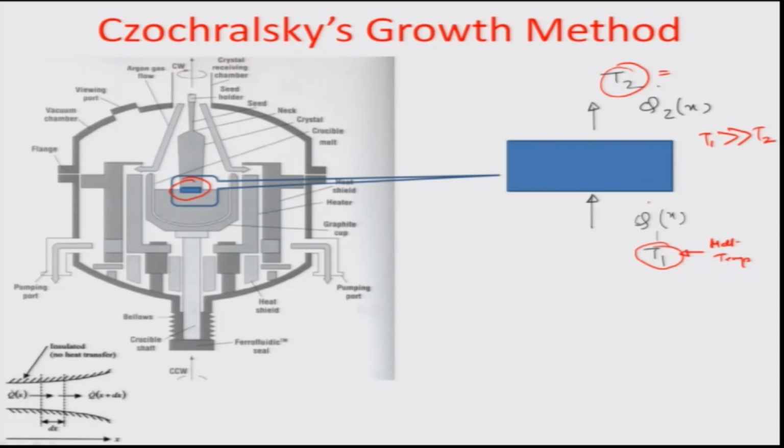is going to be a heat flow across this particular boundary from liquid into the fusion zone, into the solidification zone, and then there is a heat outflow from the solidification zone into the solid metal, which is Q2 dot. So, there is a rate at which heat is flowing in to this zone, you can call it zone of fusion or zone of solidification, and there is a rate at which the heat is flowing out from this other boundary here, which is from the zone of fusion into the solid material.